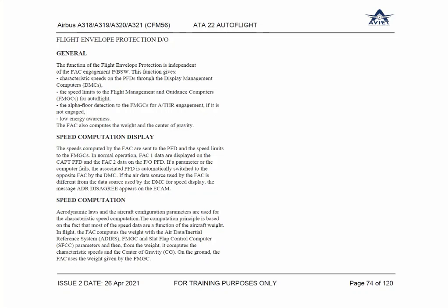You might have seen the various disagreement messages. Speed disagreement, altitude disagreement, right? Heading disagreement or check heading. These kinds of messages are displayed on the PFDs when there are different values on both PFDs, for the heading, for the altitude, for the airspeed, for the attitude. So ADR disagreement will appear on the screens.